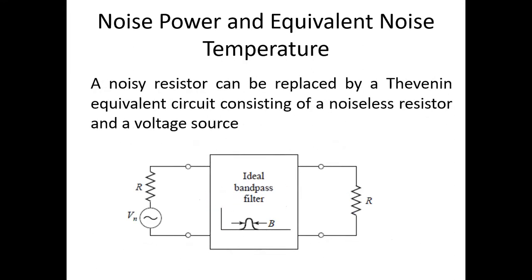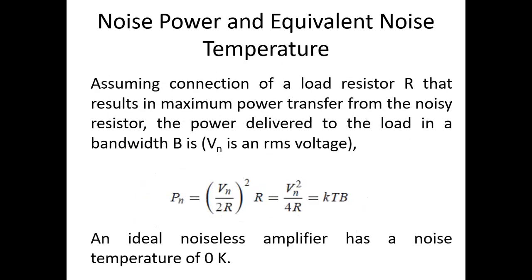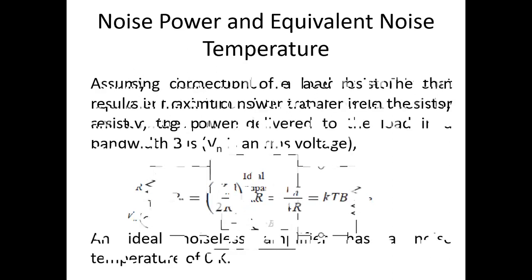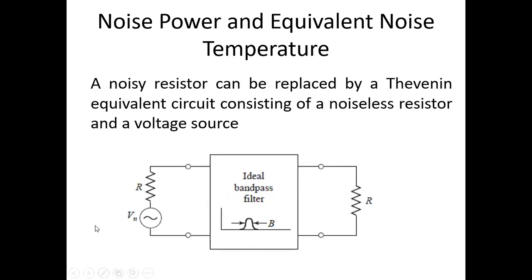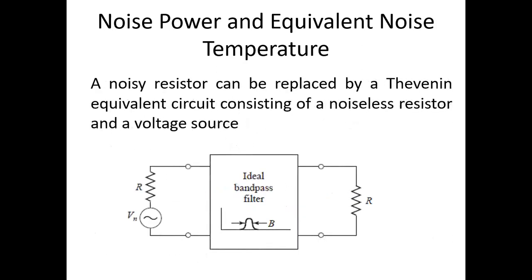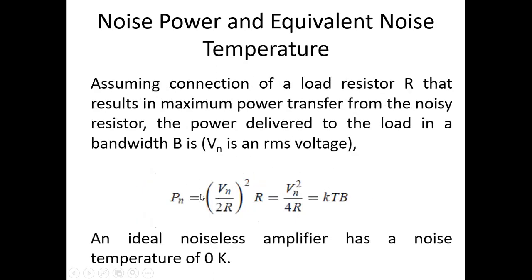So we have a power transfer equal to Vn square by 2R. The voltage Vn is now used in the circuit, so you have the total resistance 2R. The current you have equals Vn by 2R, and that current you can square and multiply by R. So you get the power at the right end. That is the power delivered to the rest part of the circuit.